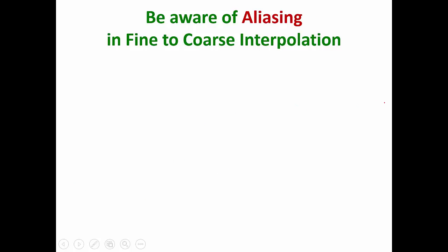Okay. One thing I want to point out is why do we need pre-smoothing at all? And one of the pitfalls in multigrid, if you can't make multigrid work, that's one of the top reasons why. That is, your smoother is not able to reduce the high frequency content of the solution error sufficiently. And if you're not able to reduce the high frequency content sufficiently,